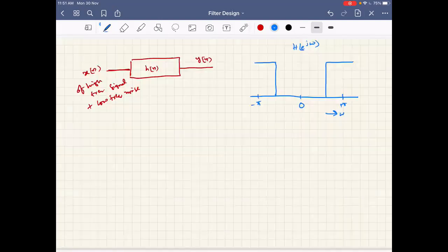Many of the filter designs happen in the discrete domain because of the advantages it has for realizing through computer. So finally, a filter may be just an operational, computational algorithm that processes the signal in a computer, or a small hardware that processes a discrete signal. So we discuss more in this video lecture on discrete filter design. However, as I said, the specifications are in continuous time, and hence we will see the relation for bringing the continuous time specifications to discrete time specifications and then design the filters in discrete time.